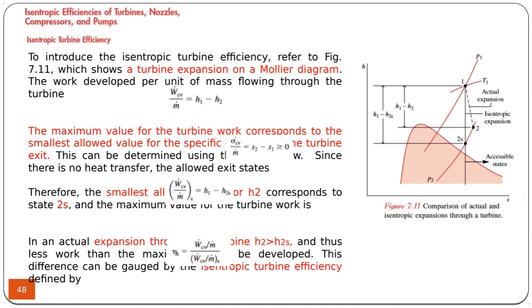So in here, this represents isentropic expansion. It has 2s, meaning that the entropy does not change. S1 is equal to S2. But in reality, because of the irreversibilities within the turbine, mostly the fluid friction between the fluid and turbine blades, the entropy increases. This is because of the production of entropy. So this much of entropy has been produced because of the entropy production. And because of this, you can see that the work output of the turbine has reduced.